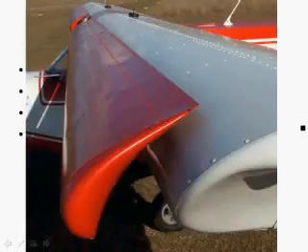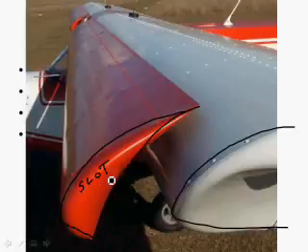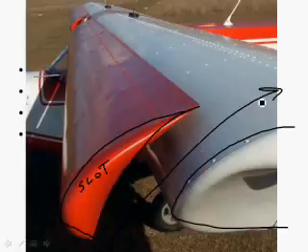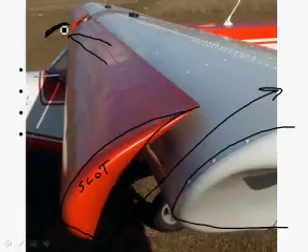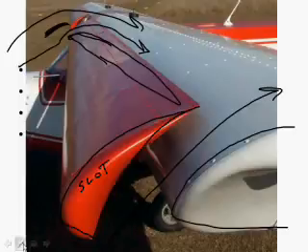On this small aircraft, here's what looks like the leading edge of the wing, and out in front of it is a slot. And effectively, this allows airflow between the slot, or through the slot, and the rest of the wing all the time. Of course, it doesn't move. It probably increases drag a little bit at high forward speeds, but at low forward speeds, again, we've got that slot on the front of our wing at high angles of attack. It'll really help us maintain airflow across the top of the wing, and of course, we need that airflow across the top of the wing to generate lift.